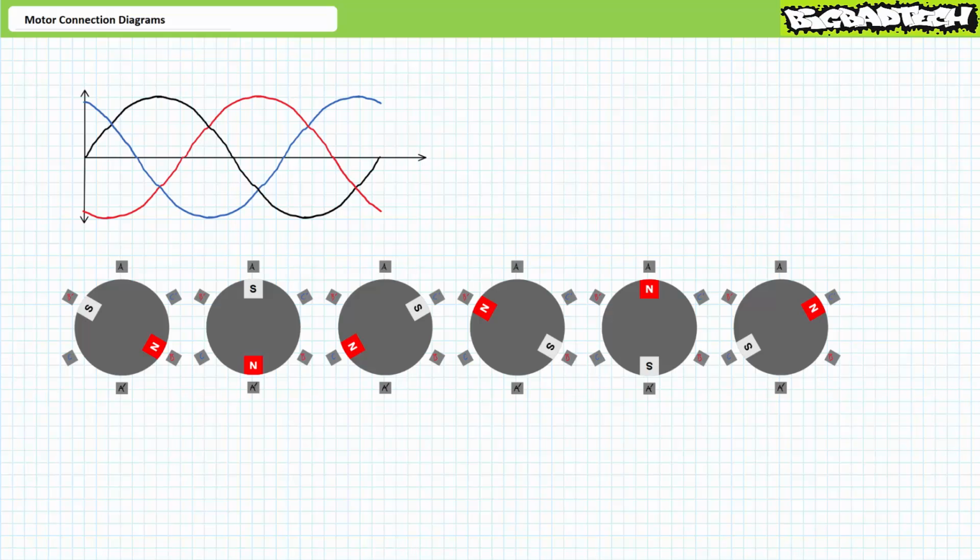This fact necessitates a brief note of caution before we begin. Do not assume these connection diagrams and terminal numbers as illustrated in this lecture are universal in nature. A thick, tangled jungle of peculiarities exist, especially for older motors and motors manufactured by shoddy companies in backward countries. It is incumbent upon you to determine the proper connection diagram for the specific motor of interest.